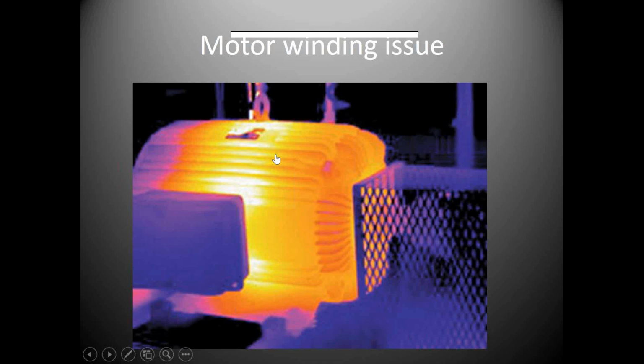Now, if you explain this to maintenance people and operators, that fan guard has to be clean and we have to have good airflow across that motor, and it makes the motor last 2 or 3 times longer, sometimes 4 times longer. I've actually done this at facilities and lowered the motor temperature 35 degrees by cleaning all the crud off the motor and off the fan guard. As people know about these failure modes, we can correct that, but it's easy to see here with this picture.